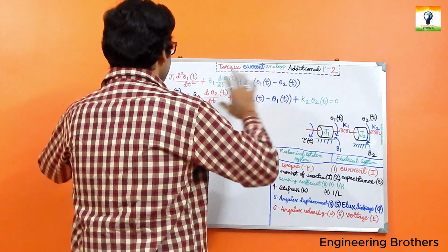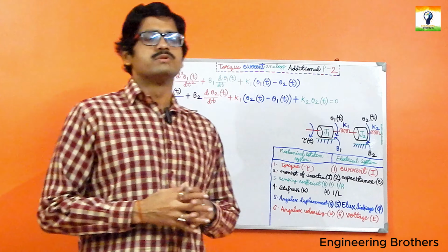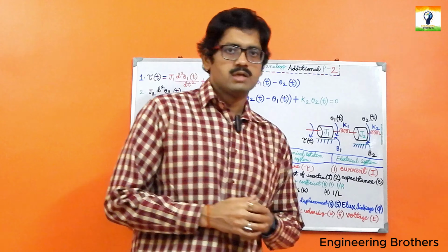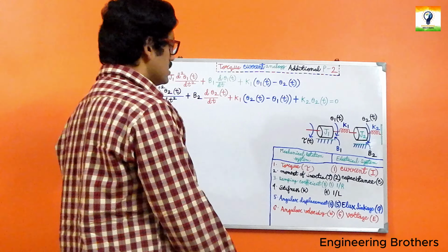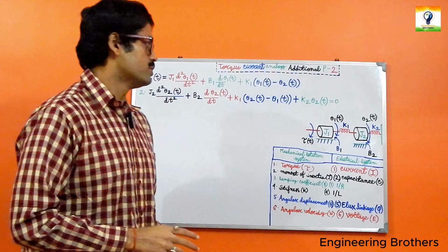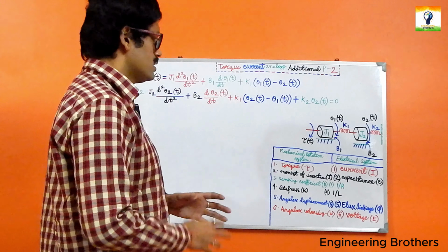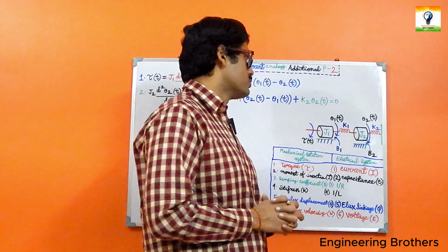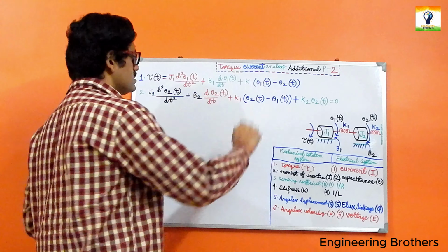Up to this differential equation formation, the equations will be the same, so we no longer need to repeat the procedure from our previous torque voltage analogies. In this present consideration, we have these two different differential equations. How do we get them? By the same procedure: first we convert the conventional mechanical rotational system into a nodal diagram. That is our first step, and in the next step, after applying the D'Alembert principle on both nodes theta 1 and theta 2, we get these two differential equations.